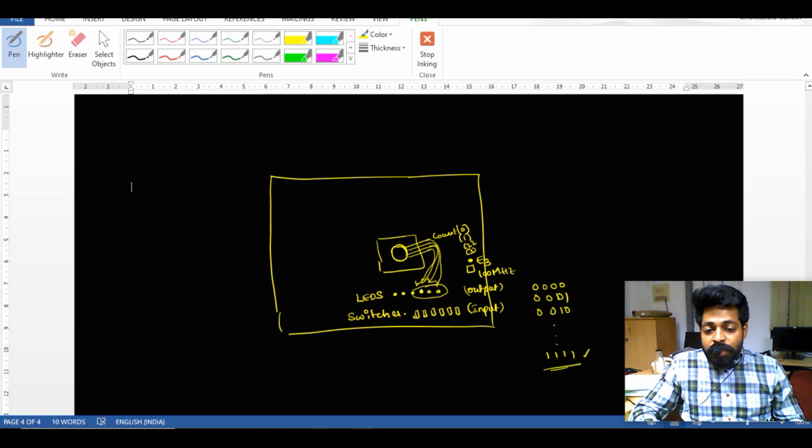So these four LEDs will become on and off. Based on that, we observe the sequence across the particular LEDs, so that the functionality of the counter is verified. For that, I will be giving two inputs over here. One is a reset for the counter. Another one is a clock. Now the clock decides at what speed my LED should be turning on and off. If the clock has a very high frequency, then the value at 0000 will go to 0001 also at high frequency.